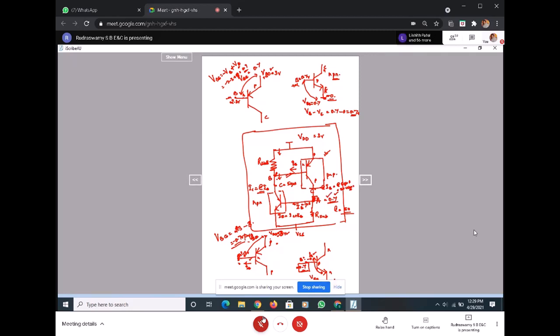That means there is the multiplication of base current, right? Because of the base current existing at the NPN, there will be collector current. And that collector current is nothing but the base current here. And because of this base current, there will be an increase. So the base current of NPN is giving rise to the collector current of NPN, and the collector current of NPN is nothing but the base current of PNP, which is giving rise to the IC.